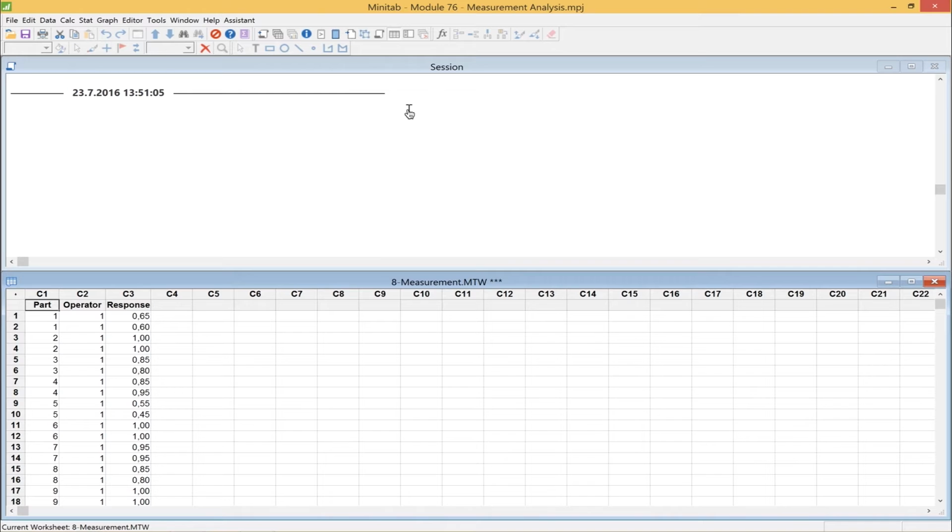Now that we're reaching the control phase, we've selected the performance measure that we want to have, and we've understood its capability. What we also have to do is check to find out, is this process measure working in a state of control relative to our process of measurement? Now remember, we talked about this in the measure phase when we were analyzing the data in the first place. But now what we want to do is make sure that this process is going to stay in a state of control and that the measurement system doesn't drift or change over time. And so what we want to do is go back and do another gauge R&R.